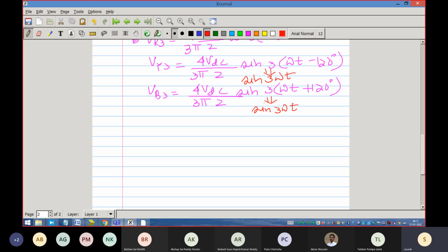Common mode voltage. You have seen that. A third harmonic voltage, you have seen that. When you sketched the common mode voltage, you have actually sketched the third harmonic voltage. Third harmonic and sixth harmonic and ninth harmonic and so on. It looked like a square waveform.